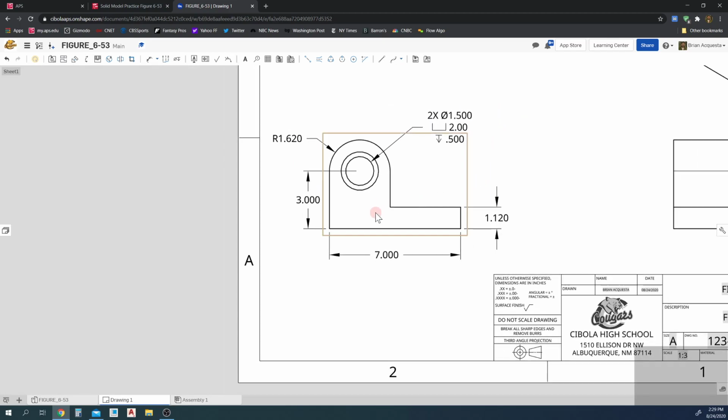Before moving to other views, and just to finish up this view, while this view is selected, I clicked on it so it's selected, I'm going to right click, I'm going to show hidden lines. Perfect. Yeah, so we get a little bit more options here. When we do threads, you can hide the threads. You can make this view shaded. I don't want to make the view shaded. I like it the way it is. I'll end up making the isometric view shaded.